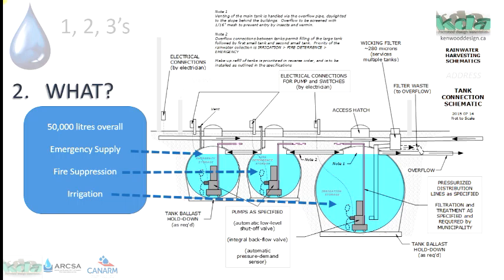And there's a backup fill in case, for example, there was a fire and the fire water had to be used. Then if there was no rain, there's a backup fill. It's called a makeup system from the well, and that's all included. It's 50,000 liters overall storage. I think there was some thought of actually increasing that size over the experience of last summer that was so dry.